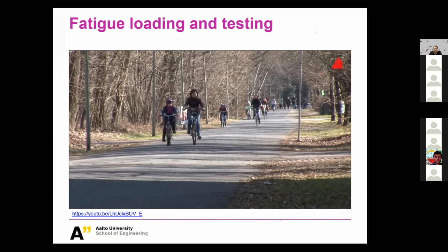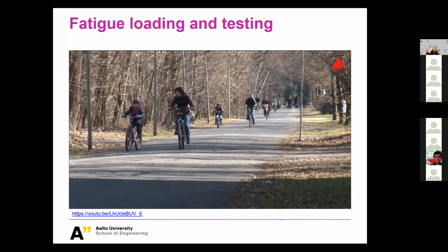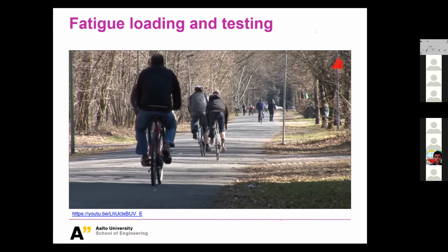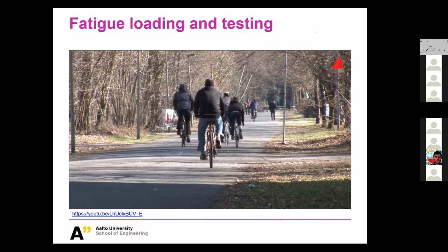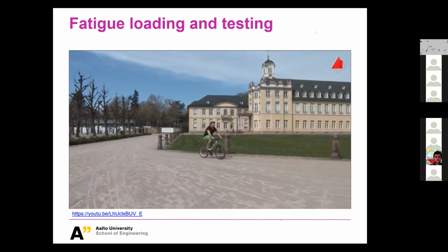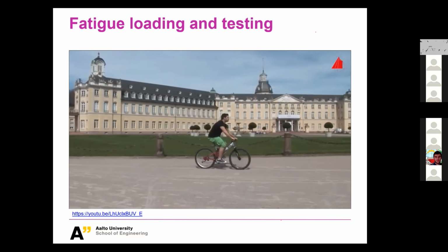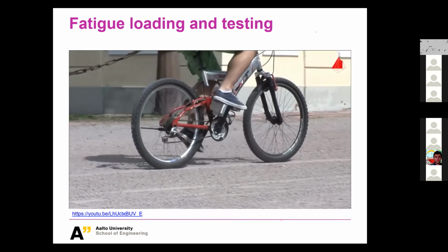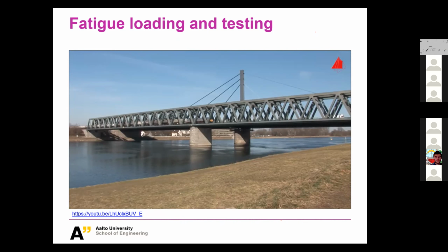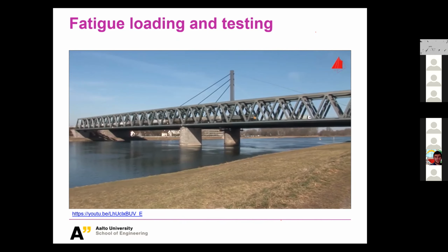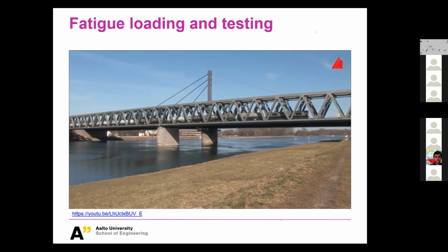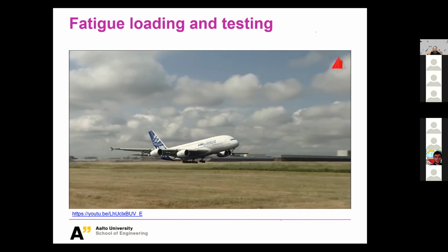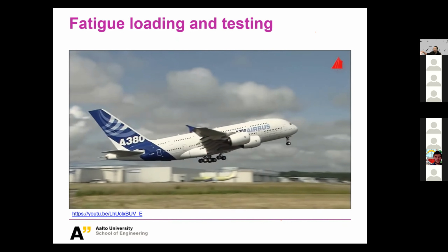Even when cycling quite moderately in the city, many components are exposed to periodically varying loads without us being aware of it. The crank arms are alternately under load, then swing back almost load-free, are under load again with the rhythm of pedaling. The spokes, the pedals, even the individual links in the chain are stressed periodically. Also, the railway bridge over the River Rhine, seemingly totally at rest, alternately has to bear the additional burden of a heavy freight train and then only its own mass. Aircraft experience quite different stresses during take-off and in turbulence than on ground.